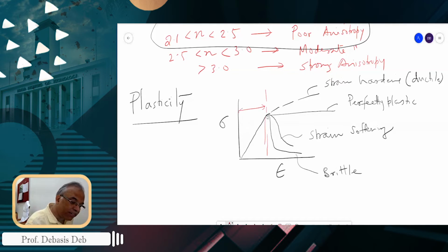material. But you see, from here to here, it is still elastic. That means with load, with stress, the strain also increases according to Hooke's law, more or less a straight line. And then here it becomes the plastic material. So each material will have a certain range where it will behave elastically. That's why even a plastic material will have elasticity.